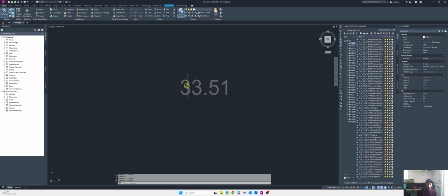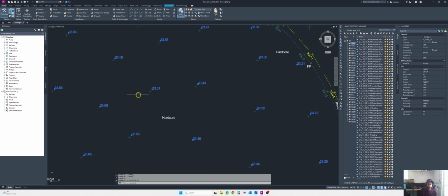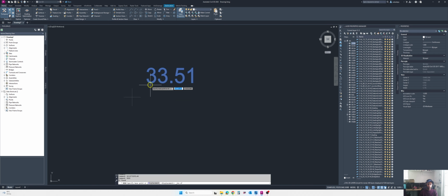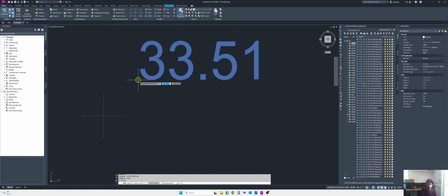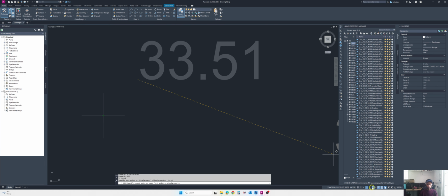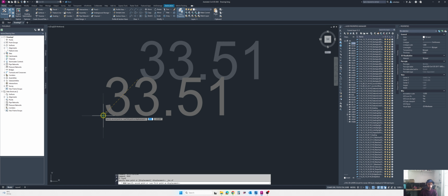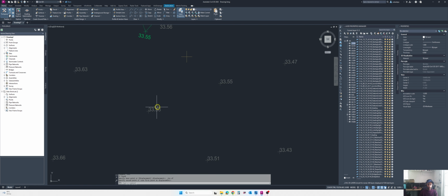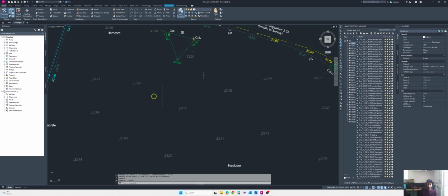So let's select all, select similar, and move, and press and hold the control key and right click and go there, insert. You can see the insert, zoom in, and you can see the green edge. So click here, and then make sure your snapping tool is on, and then you just intersection click here. Now zoom out, you can see that all of these labels have been moved to the spot levels where we want our insertion point of these text.